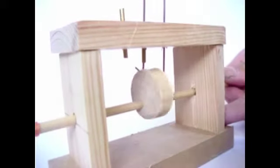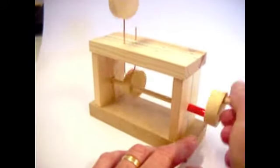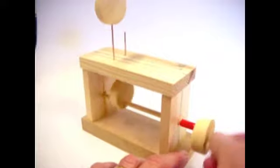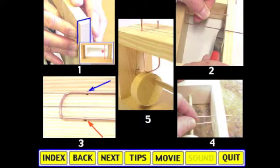There are many cam situations that need to be solved. This one of turning is one example. To stop the follower turning, you can bend the wire where it meets the cam and return it back into the automata box. See how this works. Each of the design problems will be solved by stage demonstration as shown on the screen.